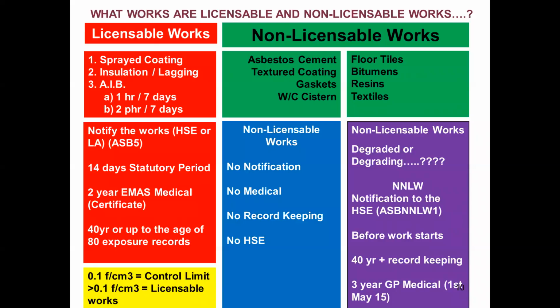But reverting back, if the works can be done maintaining the integrity of the product, removing the product as whole as possible, the odd breakage, slight breakage is not going to be a problem, that work would then be classed as non-licensed works. No notification, no medical, and no record keeping.